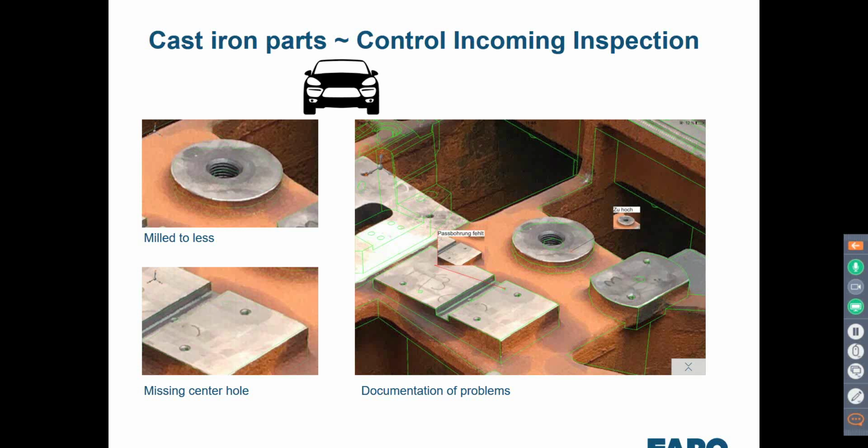Yeah, sure. As you mentioned, this causes a lot of pain, because normally there's no time for a real measurement of these parts. They come in and stand somewhere on the shop floor, and when the time comes to assemble them, after 2 days of assembling you recognize there are holes missing or some feature is wrong, and you have to disassemble and bring it to the milling machine again. This causes really a lot of time and money.